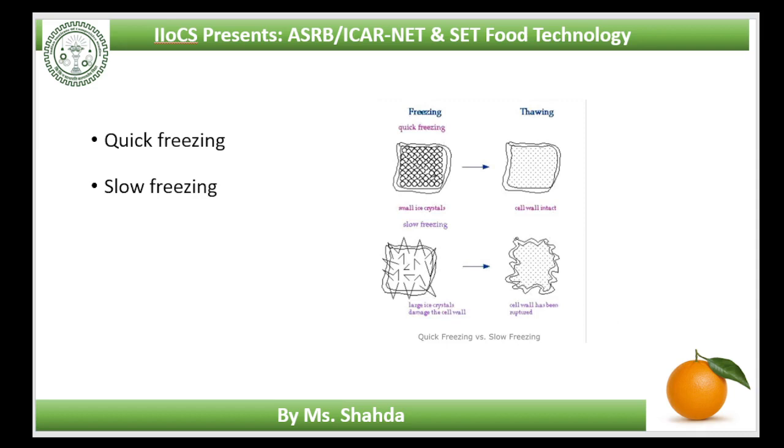During the freezing process, the product temperature is lowered and most water is transferred into ice crystals. With decreasing temperature, the liquid phase becomes more and more concentrated. As the volume of ice is about 10% larger than the volume of water, internal pressure of food may rise to 10 bar or more. This pressure is sufficiently high to cause undesirable textural changes in foods, but not as high as necessary to inactivate microorganisms.